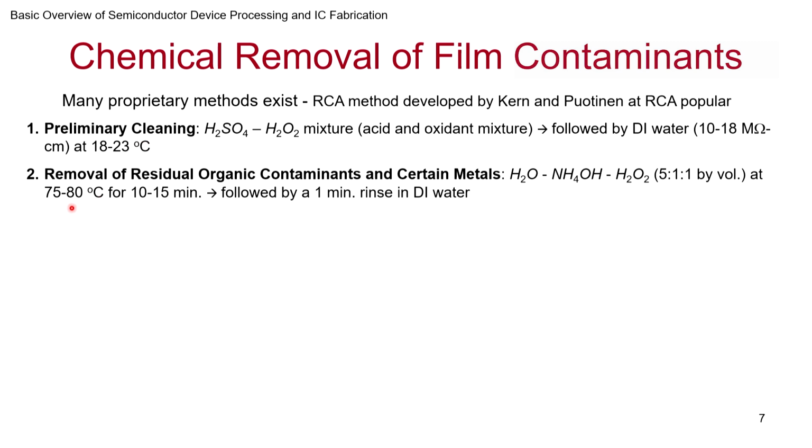And this is at 75 to 80 degrees. You keep the wafers in the bath which contains this for 10 to 15 minutes, and once it is done, you pick it up and follow with a 1 minute rinse in DI water. That way, any solution of contaminants in the solvent that is sticking to the wafer will also get cleaned up when you rinse it in DI water.